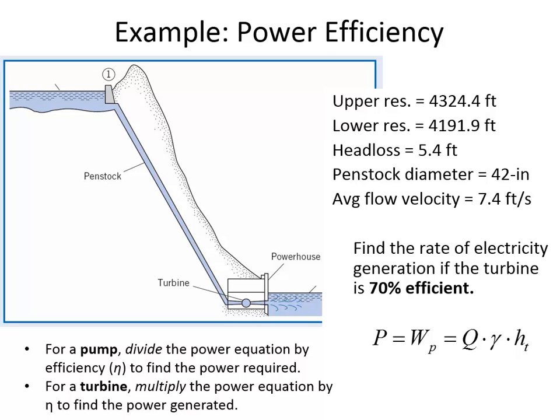Yes. Like, thinking about the head loss. Like, what exactly is that? Well, that is the pipe friction. So that equation over here has units of feet. F is unitless, so length is feet, velocity is feet per second, velocity squared would be feet squared per second squared.